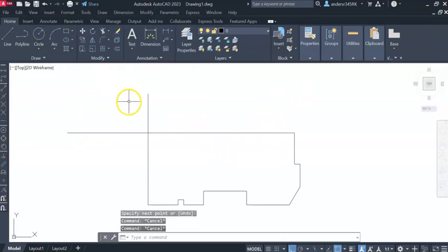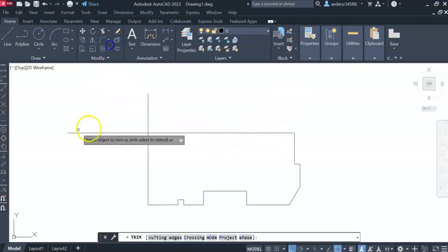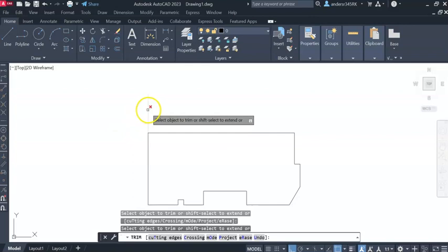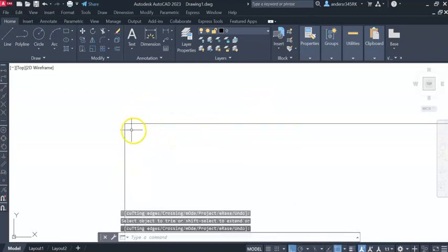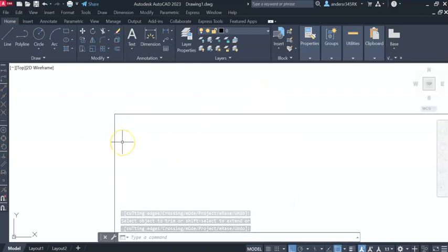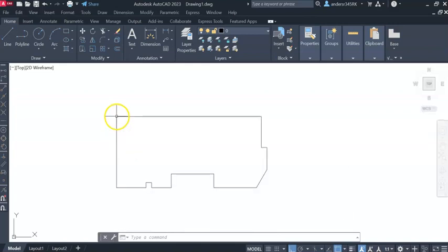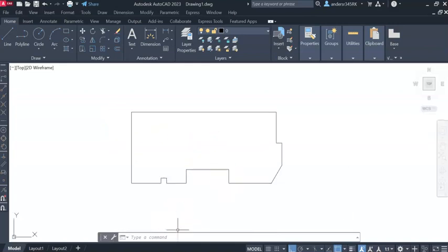Right, so I want to trim this. Go to trim. It says there, select the object to trim. So I want that one to trim. And notice there, it sort of grays it out with a little cross. It says, is this the object you want to trim? Yes. And I click on that. And I click on that. I hit enter to break off the command, and my trim is done, and these two corners look absolutely fabulous. They look great. They are trimmed right off at that intersection there. Right, my drawing is looking like this,